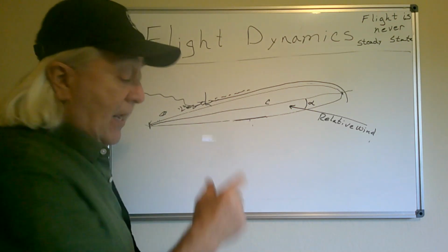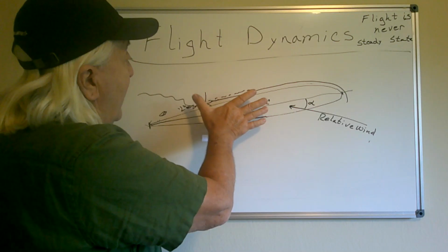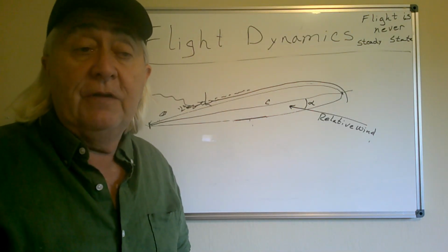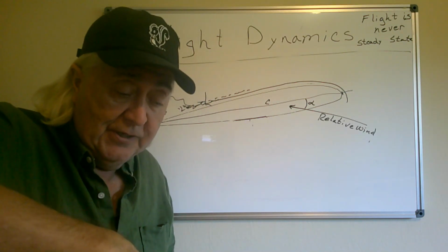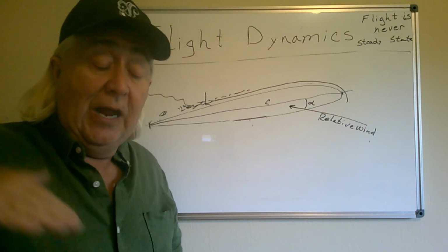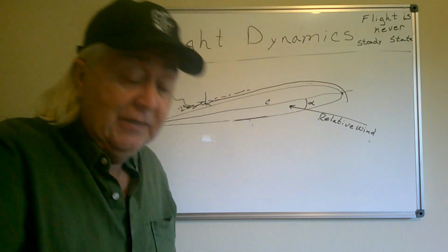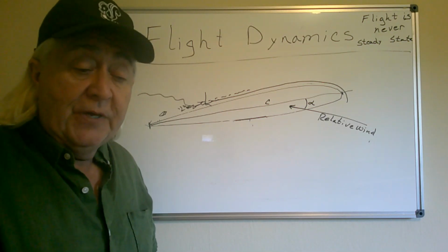and then the aircraft will go through a complete accelerated stall, which is generally that the separation occurs all at once. You might have a little bit back here, but it goes boom, and it all separates, and you lose the majority of your lift. And that's when the glider pitches down rapidly, depending on how accelerated you were coming into it and how vertical you got. And then you put the stick forward and begin your recovery.